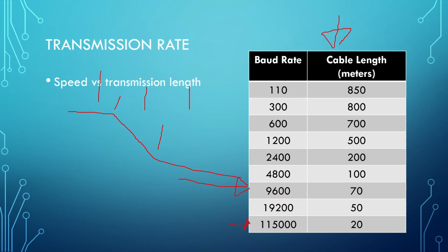But I think I normally actually see it with a 2 here, 115200. Now the other thing I will say is, while these are common baud rates, you don't have to be stuck to them. Say you feel like you need every ounce of speed you can get out of this cable, but you're at 600 feet or 600 meters.